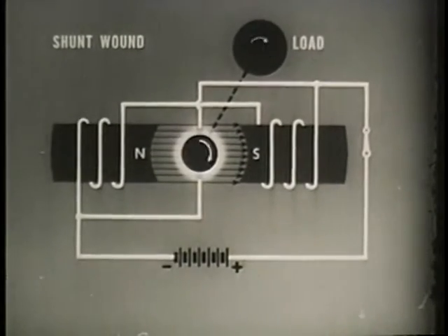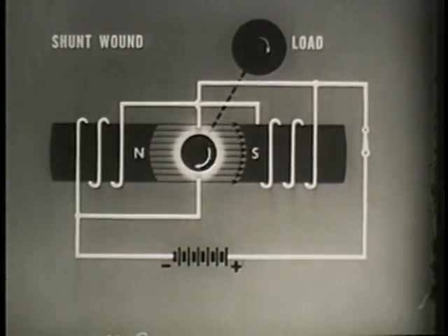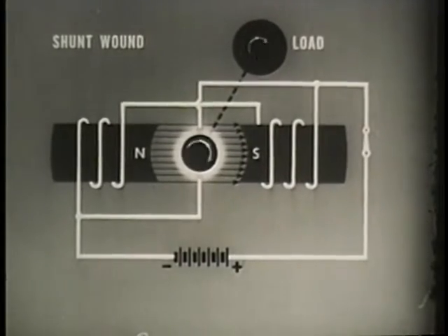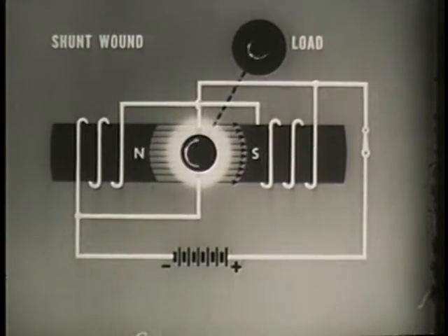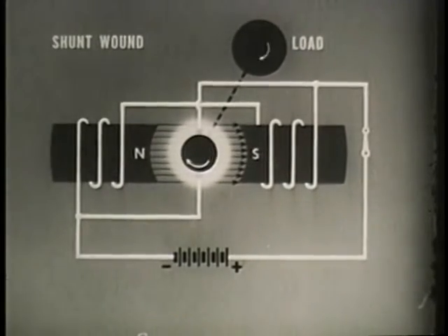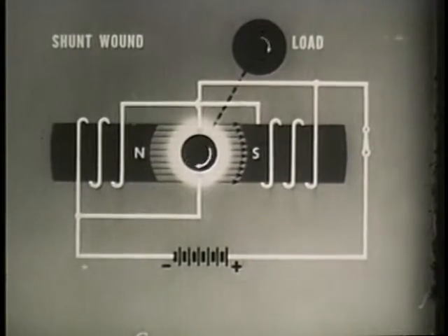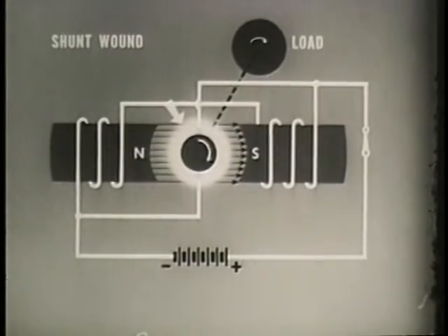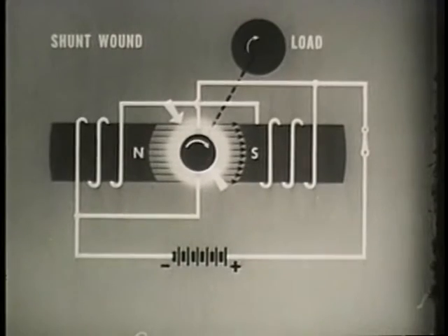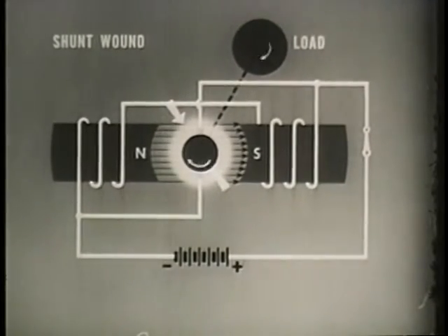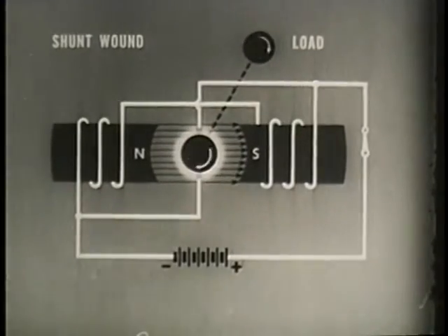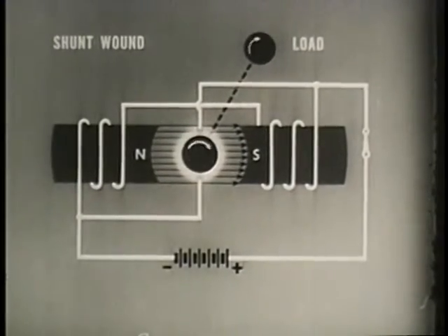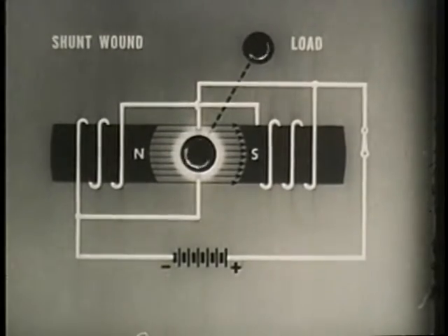As more load is applied, the speed of the armature decreases. This decreases the CEMF and increases the current input. The increase in current input boosts the coupling between the field and armature and increases the torque, causing the motor to resume approximate running speed. A sudden reduction in load will not damage the motor because the field current is independent of rotor current in the shunt wound motor.